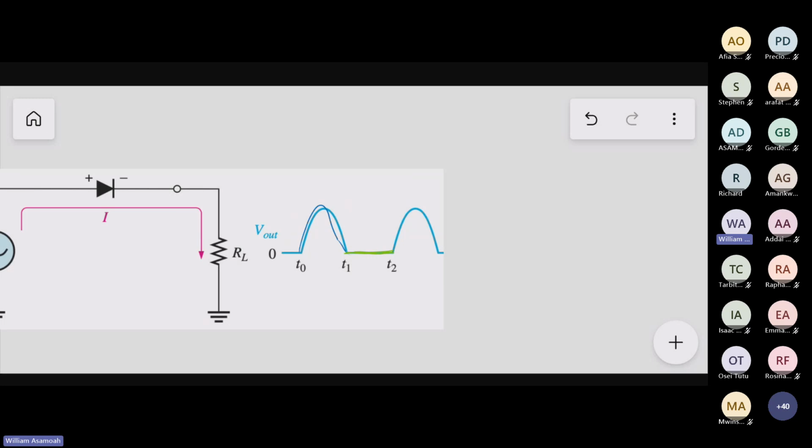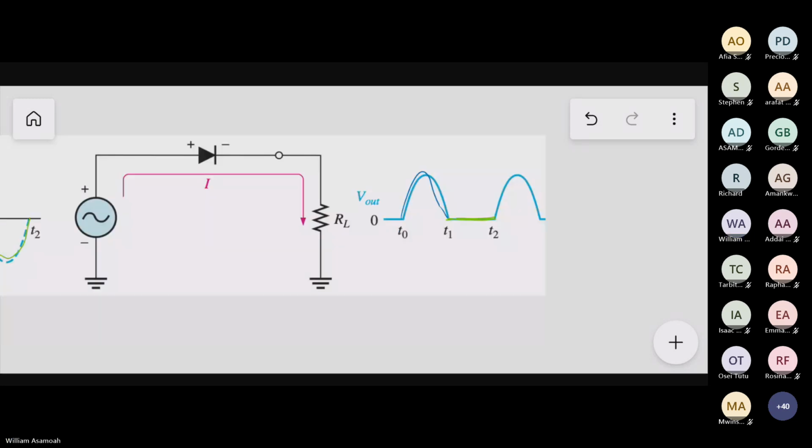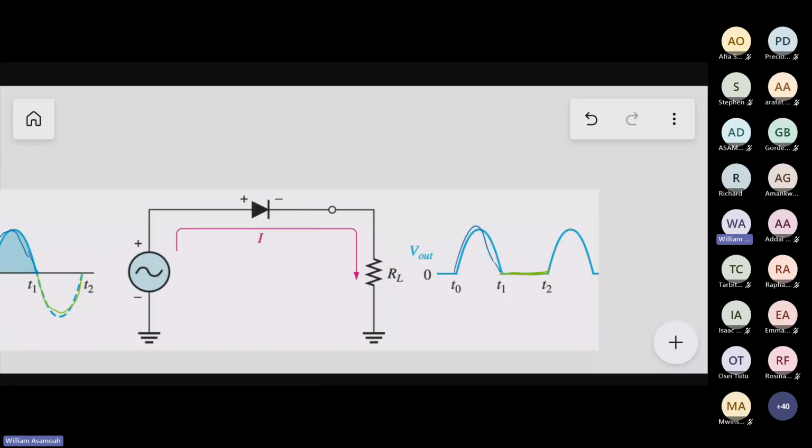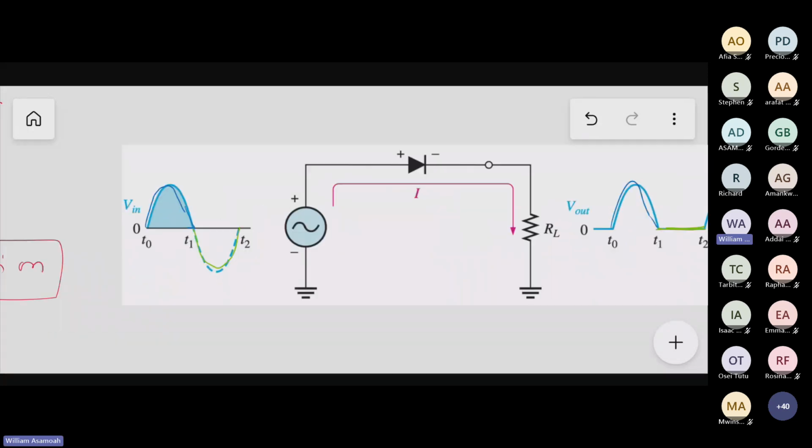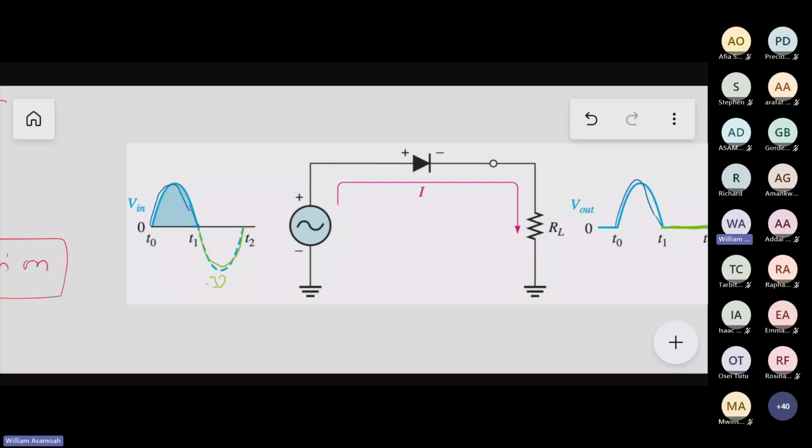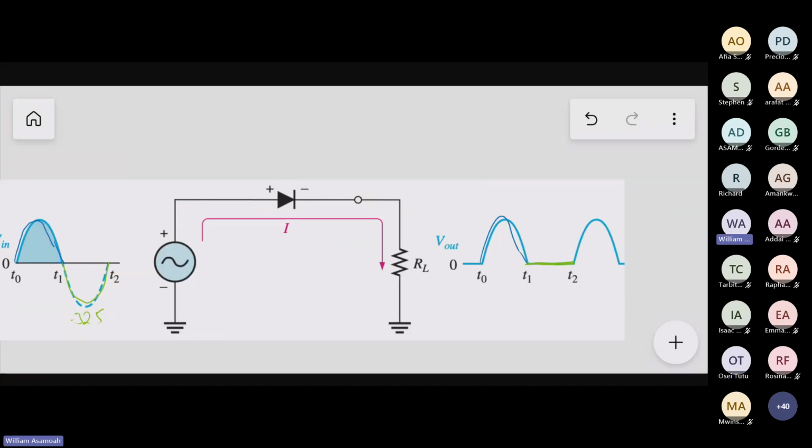Great. Now, that is where the reverse voltage comes in. That is where the voltage rating of the reverse comes in. Now, we know that this maximum side is negative 325. So that means that your diode must be able to withstand a maximum reverse voltage of negative 325. Is that right? Yes, sir. Great. So that is where your question comes in. That's why it's important.